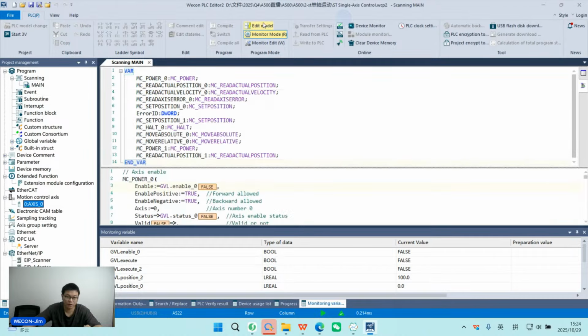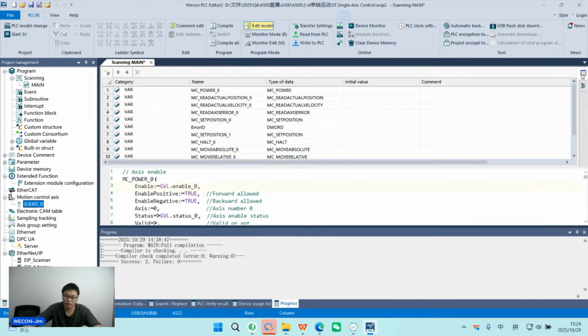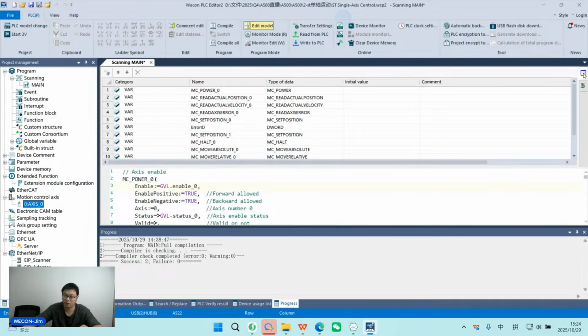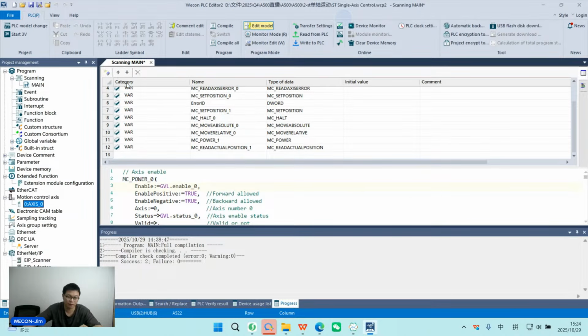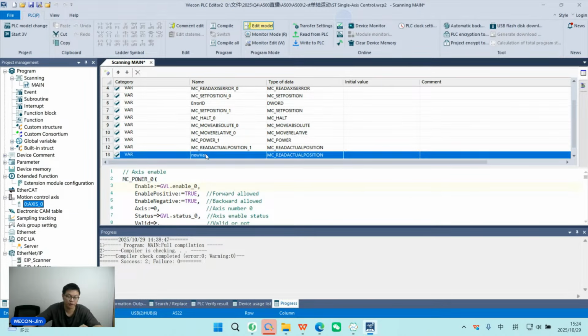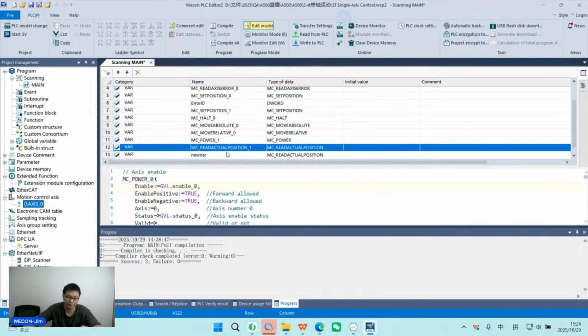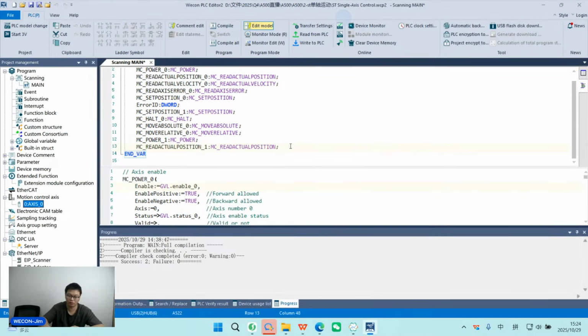Okay, for the ST, if you want to create a new variable, you can switch the input type. Here we have table type and list struct type. In table type, you can click this button to add a variable, name the variable, and set the type of the variable. And you can also use this form to create each variable.